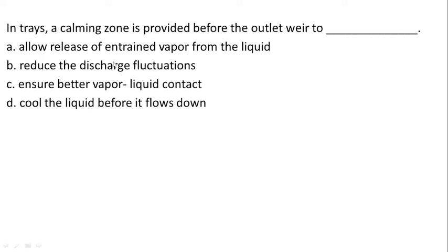So here they have asked by which mode entrainment flooding is occurring. What is the reason for entrainment flooding, vapor or liquid? Vapor. Okay, and for downcomer flooding, it is liquid. So the answer will be option A. Option A. You got it, no?